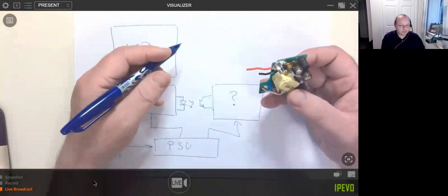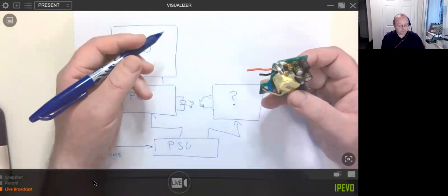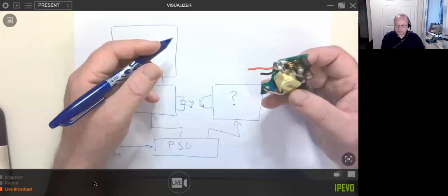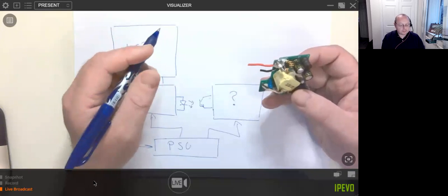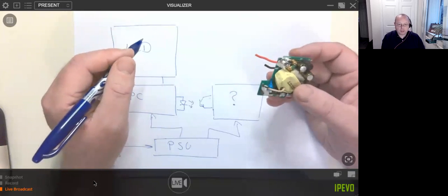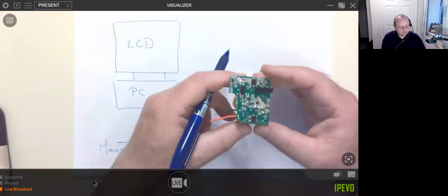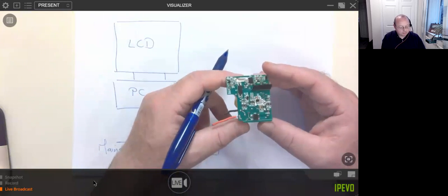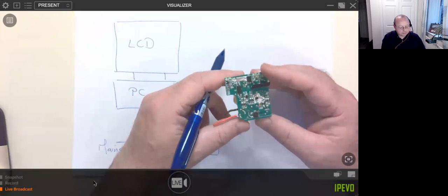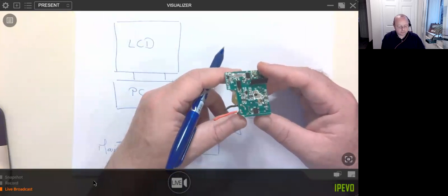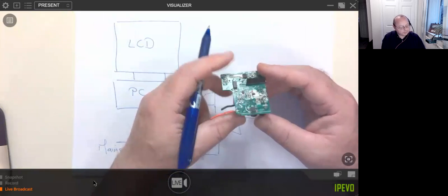And yet the standard, 61000 for power supplies, demands 2 kilovolt surge tests. So how does this circuit, with no protection apart from a fuse, survive 2 kilovolt surge tests? Well, it didn't, it blew up, obviously.